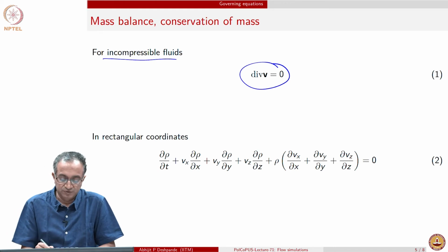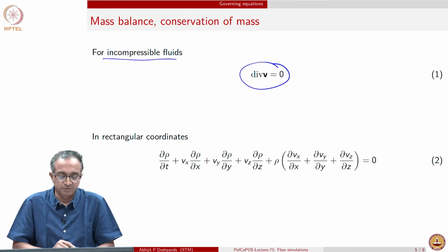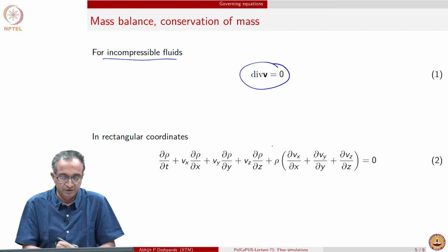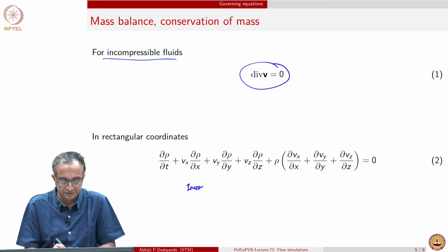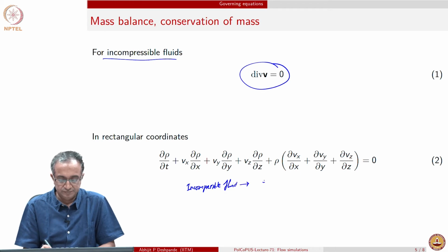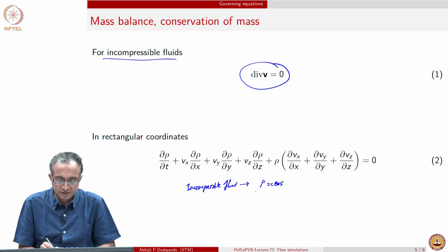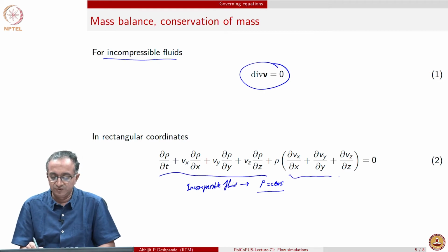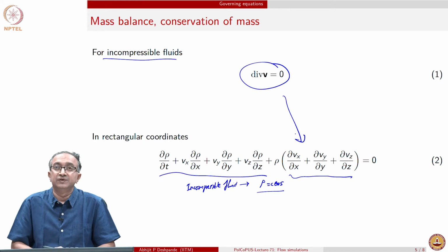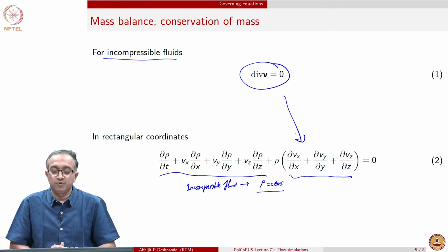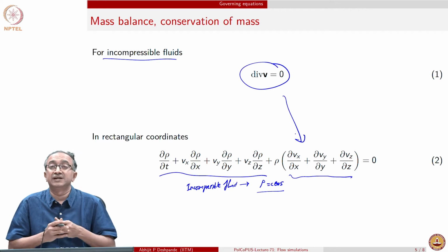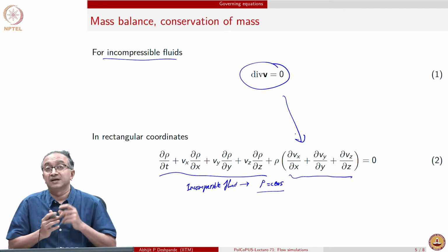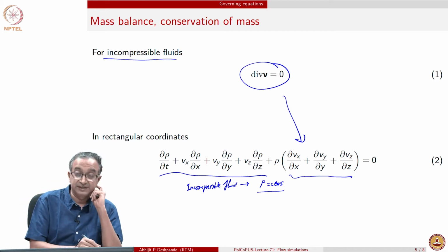And so, for example, in this you can see that for incompressible fluid anyway all the terms will identically go to 0, because for incompressible fluid, since rho is a constant, you can see that all of these derivatives will go to 0, and then we are only left with divergence of velocity being 0. So, this is one important component. So, what this says is velocities are not independent in different directions, as they depend on x, y and z. The variation is related to each other.